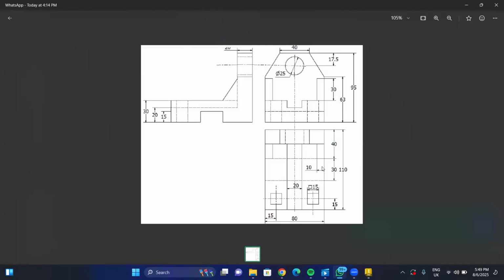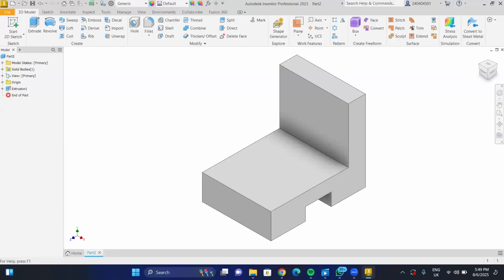Now, since it's slant, there are two ways you can do it. I'm going to take the easy way out. One of the ways is that you can create a plane and draw your sketch on your plane and produce that web. Well, I don't want to start confusing you now, so I'm going to create a block, like a rectangle on that block. I will create a cuboid and I will extrude again to produce that. It might be longer, but it's easy for you to understand. So as you become perfect in drawing, you know how best to deal with some of these.